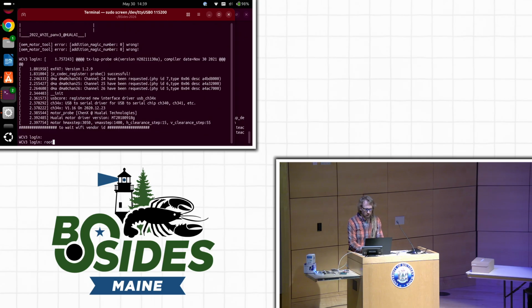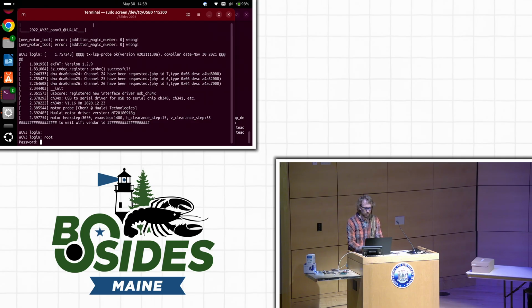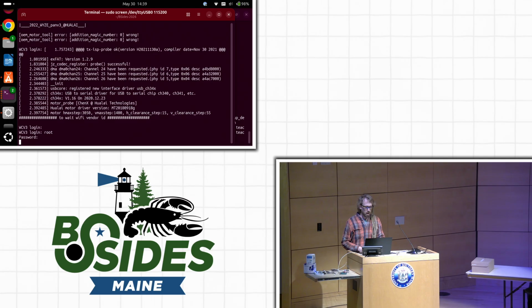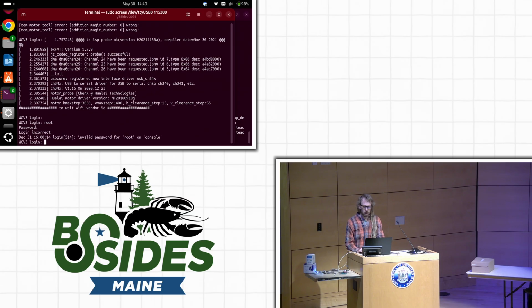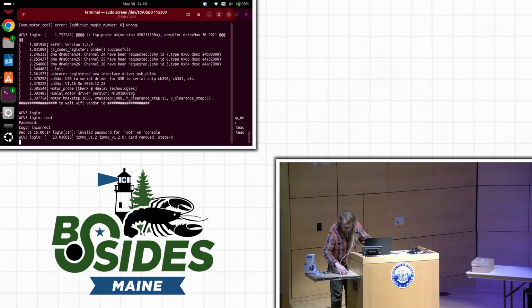You get to here and you don't know the password to log in. That's a pretty typical experience over UART with these types of vendor cameras. If I were to switch chips back and reset this, I believe what I have flashed on here now simply won't boot because it's our standard image for this camera. If I unplug, plug it in, you see nothing. This is the SoC rejecting booting something because secure boot's enabled.